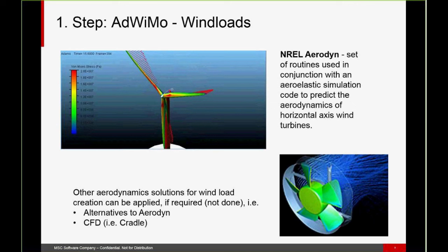It's not connected at the moment, but if you are interested, not for certification, of course, because the simulation time would take too long, but in a very detailed analysis of your blade behavior in combination with the rest of the structure and your wind turbulences, then a connection to a CFD code can be your choice to get a deeper insight into the behavior. This is not done at the moment. This is just shown to explain that we have the capability, if needed, to connect a CFD code.